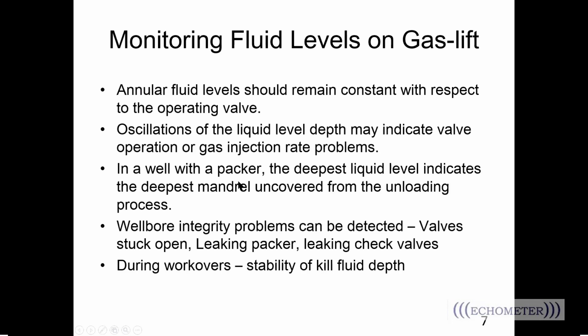All right, so once we have a stabilized gas lift well, the annular fluid levels should remain constant with respect to the operating valve. Oscillations of the liquid level depth may indicate valve operation or gas injection rate problems. In a well with a packer, the deepest liquid level indicates the deepest mandrel uncovered from the unloading process. Wellbore integrity problems can be detected, and we'll look at some examples of this: valve stuck open, leaking packer, leaky check valves.